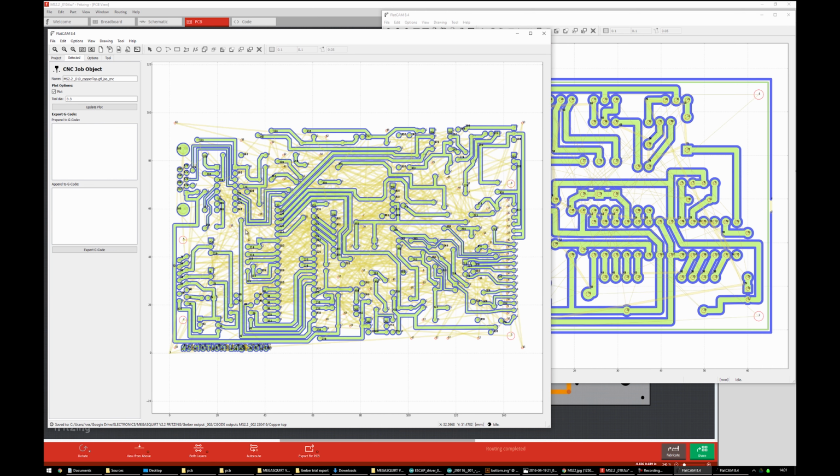Now we need to open the copper bottom. Sorry, I'm just having a look at these holes here. Here I've used the preset built-in library components in Fritzing, so it's obviously figured out that it needs to cut around this hole, the mounting hole for the connector. It didn't do the same for my ones because these are just holes that I added, not wires.